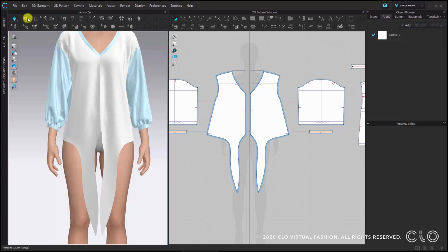I will now continue with the select move tool and place the pins by pressing down my W key and place a pin on both sides. Now it's important that the simulation is started, and now you can move the pins around in the 3D window. You can simply move a pin by using drag and drop, but you can also make use of the gizmo.